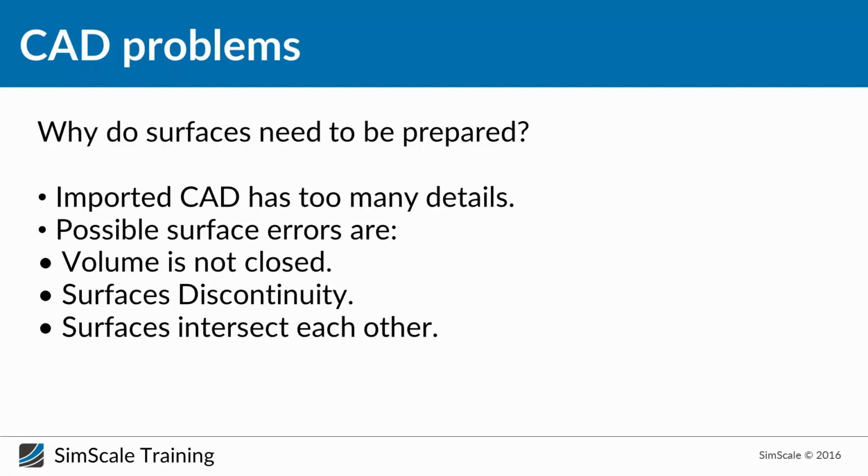Anyone who has worked with CFD before knows that when you get a direct model from the CAD, it's sometimes really difficult to put this model directly in the CFD software and start doing your mesh and running your simulation. First of all, you have to go through this really important part, and nowadays in CFD, pre-processing is really the most important part, because approximately all the software have the same solvers, but the pre-processing is the most important thing.